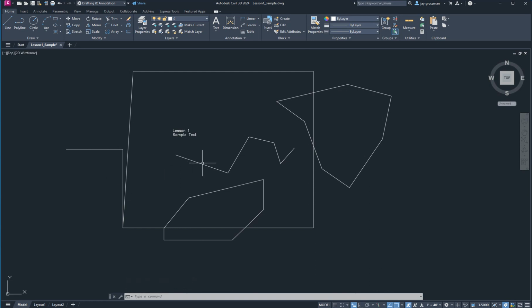So if you click on one of the lines and you hit E, and then hit spacebar. Spacebar is like the enter button in AutoCAD. You can click something and type in E, which means erase, and hit enter, and it disappears. Or you can click something and type E and hit the spacebar. The same thing happens. Spacebar is equivalent to the enter button or the return button on your keyboard. And the enter button will also repeat the last command, same as the spacebar does. So they're interchangeable.